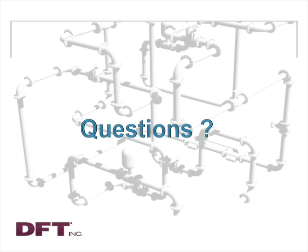Well, that's a very good question, actually. And the only valve that's really going to work in that situation is an inline or silent check valve, also known as the nozzle style check valve. A swing check will work in that application, but it's also going to cause a high level of hydraulic shock or water hammer when the pump shuts down or the flow stops for whatever reason. And all that shock can be avoided with a nozzle style check valve or a DFT silent check valve. It's the ideal valve for that application, and it should be the only valve that you consider in that circumstance.